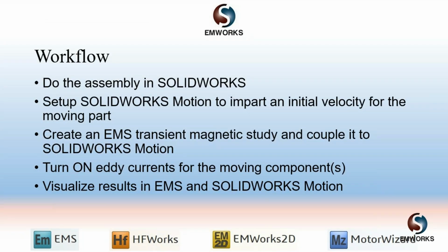Now, let me just recap some of the workflow that you saw in the demonstration that I used. First thing that we need to do is create the model inside SolidWorks. Since most of you are users of SolidWorks, that would really be an easier task. Then one needs to set up a motion simulation inside SolidWorks. Basically, the motion simulation gives the model, the disk, an initial angular velocity, or an RPM.